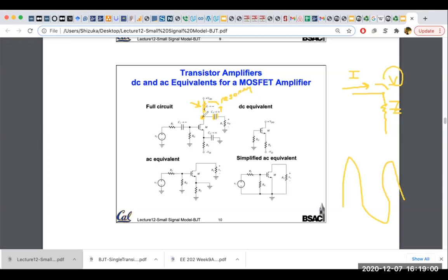If I just put a small resistance here, short to the ground, you will kill all the voltage, right? Because all the current will flow through this resistance. So that's something that you don't want. That's why the most basic thing is putting a choke here so that this sees infinite impedance here. Okay? And it just goes to the load directly.